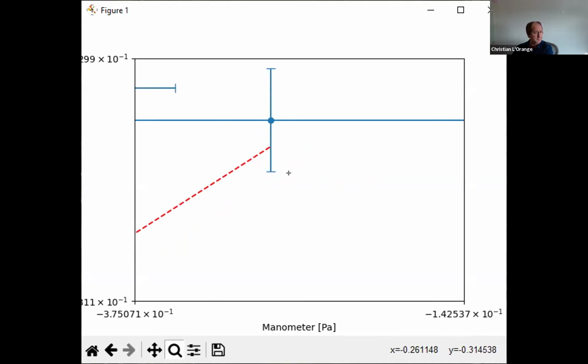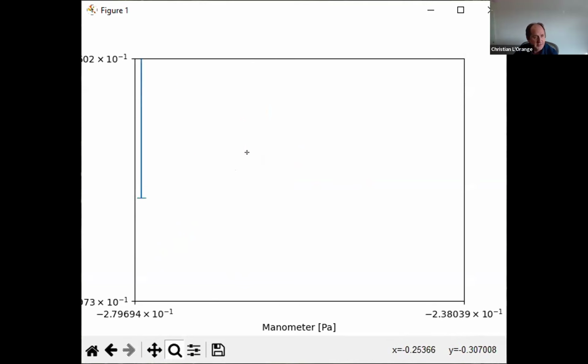We seem to lose most of our agreement at upwards of like 30 pascals, which I think is way more than what you guys are caring about. That's where we started to see deviation, and I think that's just turbulence through the pressure sensor that we have. The way it works, it actually pulls a tiny fraction of air across an element due to that differential pressure. When the pressure gets too high, it's too big of a flow, and we're getting too close to the upper range of the detector and it gets noisy. But all looking promising is the long and short of it.